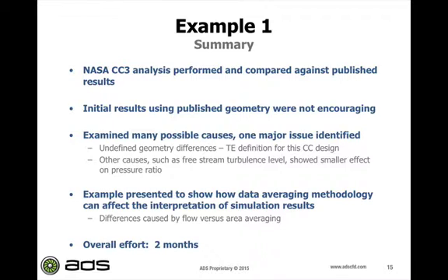Next one, I just want to demonstrate that the averaging of your data can also impact your comparison. I just want to make sure we are aware of this problem and the need to work with experimentalists to understand how they reduce the data. This root cause analysis took us about 2 months to figure out, because that really brought us to make a new capability in our mesh generator, to make it capable of generating a mesh with a constant radius cut. So this really gives you a summary of our first example.